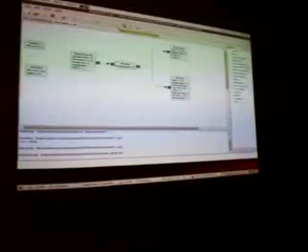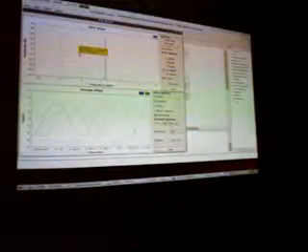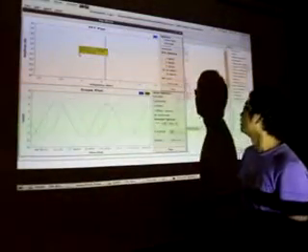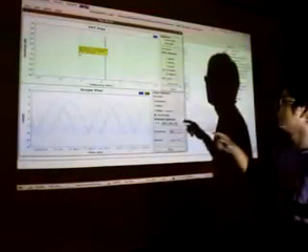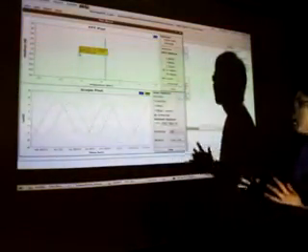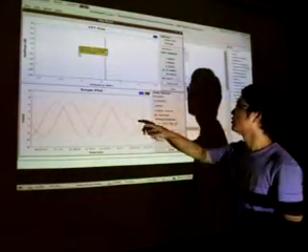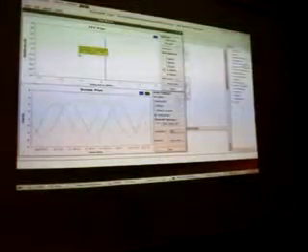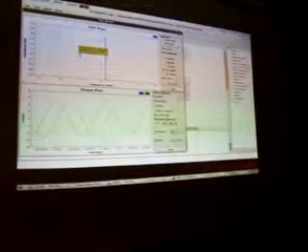You can execute it, and then it will generate a GRC file, and you can run it by clicking this button. And you can see the frequency domain and the time domain. The signal transmitted was decomposed into I channel and Q channel. So there are two sinusoidal waves here, and one is the spectrum. And I will show how to do it step by step.